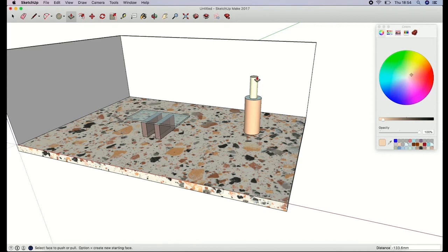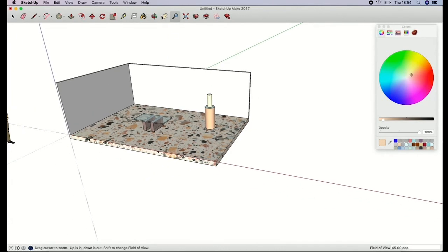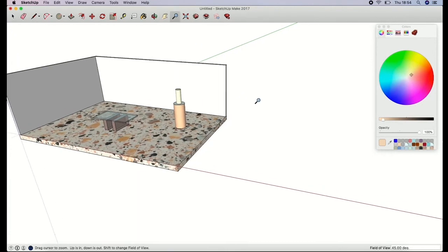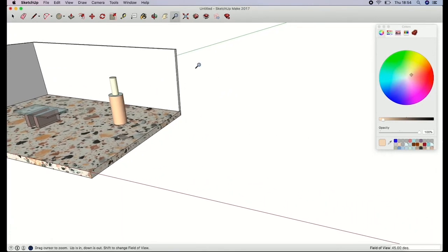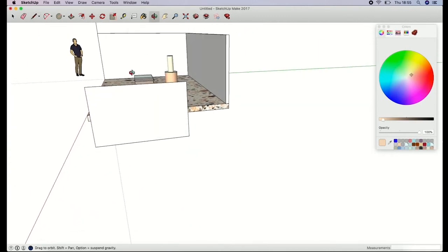So I'm also going to make a chair for the space. It might be easier to do this out of this main diagram, and then I can also show you how to use things to adjust the scale. So if I go into this clearer bit of space here just by moving it across, sometimes it's easier to make things in profile and then extrude them across. So if I make sure I'm in line with the blue axis, the green axis, and then have something that is also with the green and in line with blue, I can then rotate round. So I'm working in that profile.